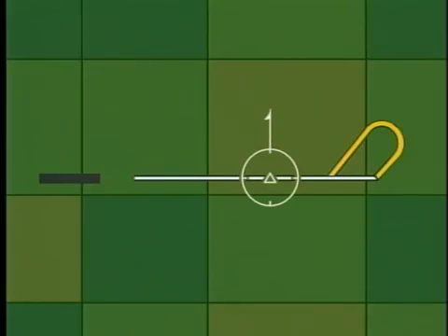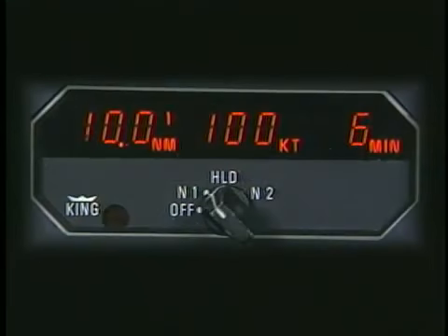Another consideration with non-precision approaches is whether you can land straight in from the approach or if you need to circle to land. Some approaches have the final segment closely aligned with the runway. In most cases, you can make a straight-in landing from these approaches. When the final segment does not meet the criteria for a straight-in landing, a procedure called a circle-to-land maneuver is usually required to align your aircraft with the runway. Another concern is whether or not DME is available or required for the approach.